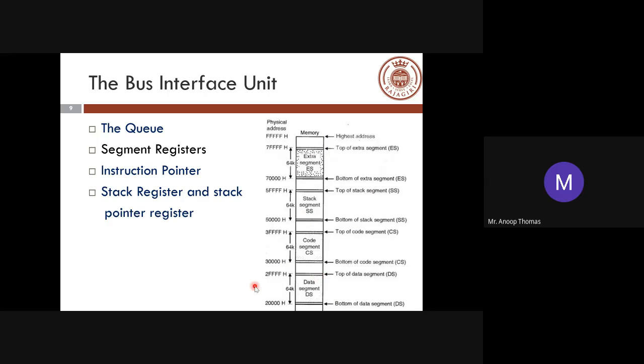Okay, so hopefully this is clear. So you have a continuous set of divisions from 2000 to 3000, then there is a gap from 4000 to 5000, then again there is a gap between your 6000 and 7000, which can be used for anything. But this is the standard way of dividing your memory into different segments. Along with it, you have other memory options which are available, which you can use. So this is the standard way of dividing your memory in the case of the 8086.